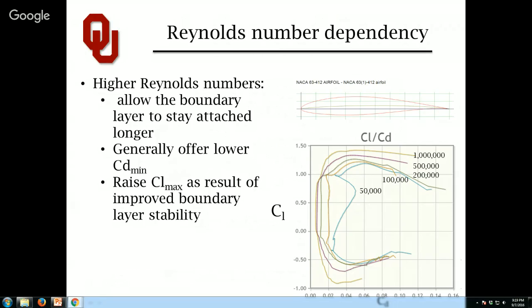I do believe this is the slide we left off on, where I had a little bit of a hurried explanation of Reynolds number effects on airfoils. I don't want students to think that everything about an airfoil changes only due to Reynolds number. A lot of the non-dimensionalization we do into coefficient of lift, coefficient of drag is very, very useful for modest changes in speed, for comparing things against different velocities, different flight ranges, etc. But sometimes when you're getting too disparate from the original case in which you've tested something, it is important to make sure that the underlying aerodynamic qualities have not changed due to Reynolds number.